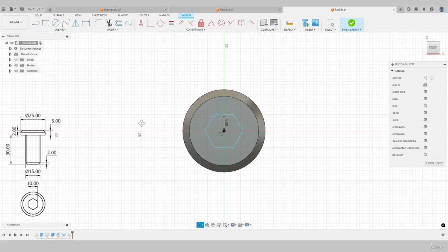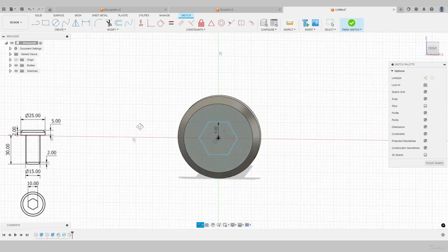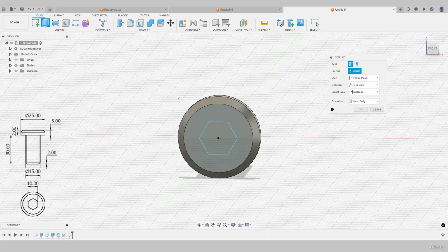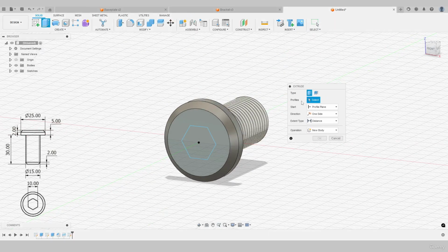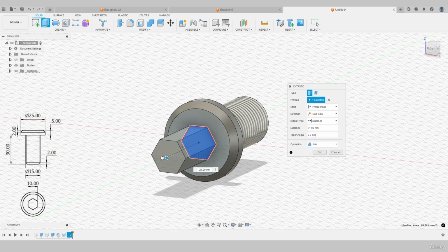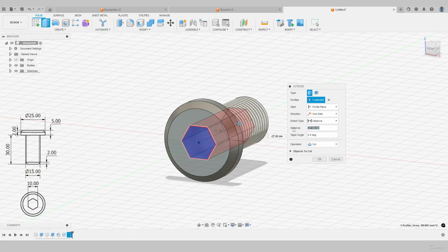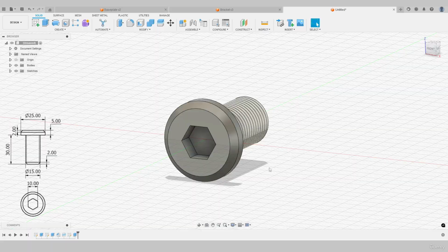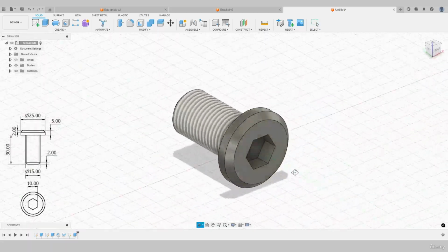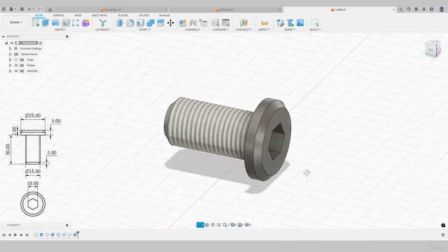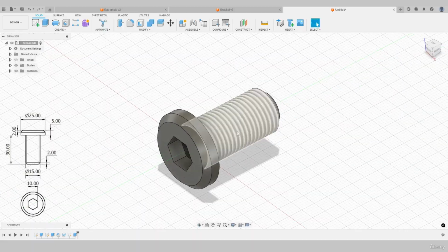So okay. Looking good. We just need to remove some material there. So let's come under Solid, go and Extrude. Make sure that we select the right profile. So we want this one here. And let's just make sure that's in the right direction. Okay, so it's a negative dimension. So in this case, it will be -5. Leave everything else as default. Operation set to cut. Press OK. We've got our keyway. And there we have our fastener. And we're now ready to form our assembly.